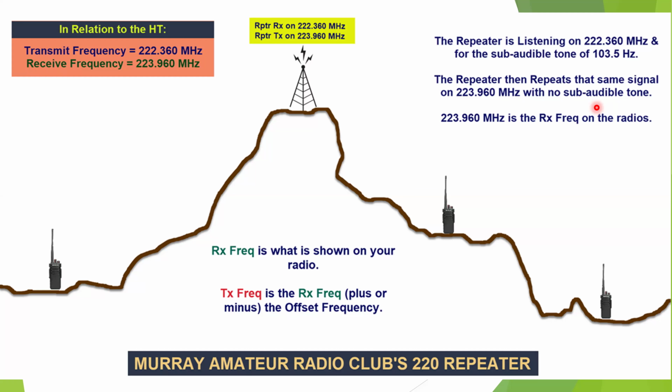When we program our radio, we are programming the transmit CTCSS, which is the repeater's receive PL tone. We could have just as easily programmed the repeater to also transmit a tone so that you would have to have your receive tone configured in the radio for the squelch to open up. We don't do that. We leave it open. So the only thing that's required is the transmit from the HT, in this case, to the repeater with a tone of 103.5.